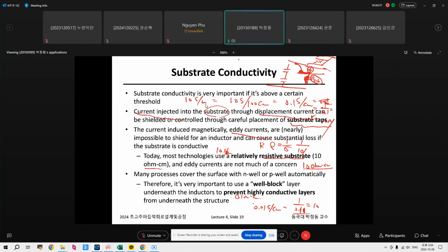Okay. This is the structure and symbol of MOSFET. So this is effective length, gate length, and this is effective gate length, drawn gate length. So the L effective is always smaller than the real drawn gate length. Okay, because of side diffusion.